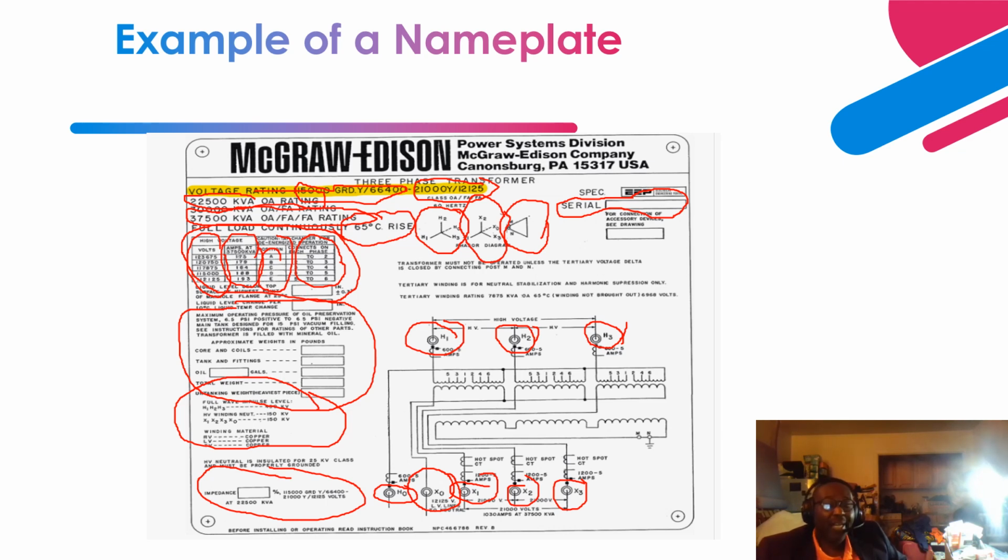So a temperature gradient is added to the temperature of the heater to achieve the hotspot temperature of the transformer. So this is a typical CT that has been installed in each phase to be able to determine the winding hotspot.